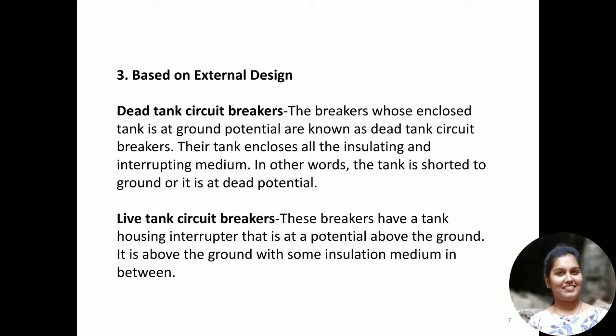Next one is live tank circuit breakers. These breakers have a tank housing the interrupter that is at a potential above the ground, with some insulation medium in between. The one which is placed at zero potential or shorted to ground, we call a dead tank. Whereas if there is a certain amount of potential, or it is above the ground with some insulation between them, then we call it a live tank circuit breaker. Okay, so these are the two different types based on the external design.